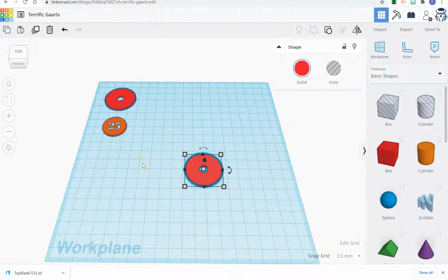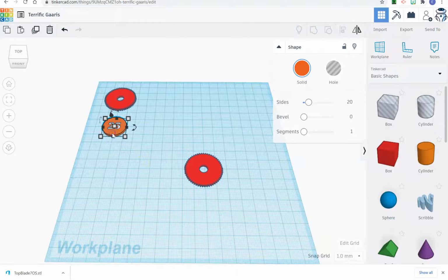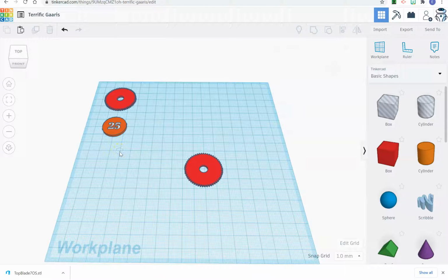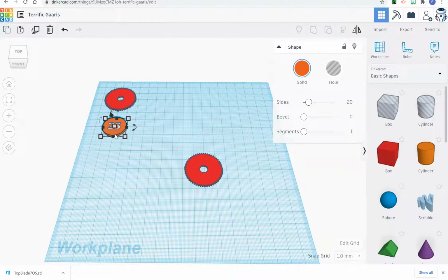Another thing that you're going to want to do, and I've already done it here, is figure out the size of a US or Canadian quarter, if you're Canadian. The US quarter is 24.26 millimeters by 24.26 millimeters, and it is 1.7 millimeters high. I usually create a version of that so I can get a sense of size. So do that when you have a moment. Create a disc that is that size. You can use a cylinder and size it accordingly.